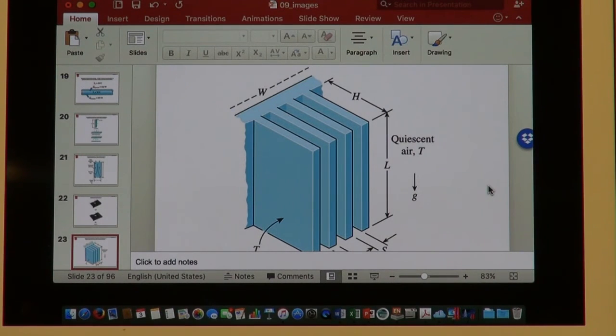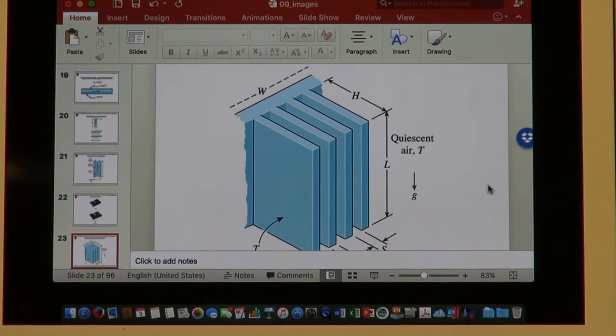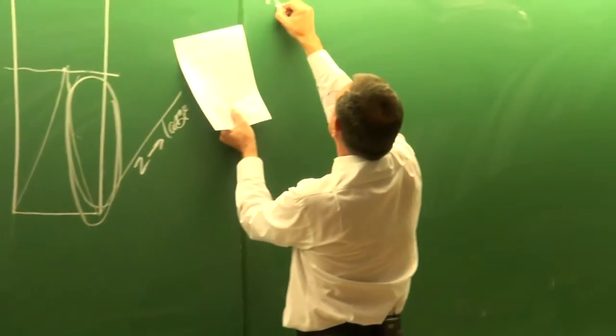But in general, this is also an application of a flat plate. You agree? But it now depends on the length L. If the length becomes very large, then a significant part might be fully developed. So again, it depends on the length. Now if you look in the textbook, you will see there are many equations available, and again they are divided into the constant wall temperature cases and the constant heat flux cases. So for example, for the case where T is a constant,